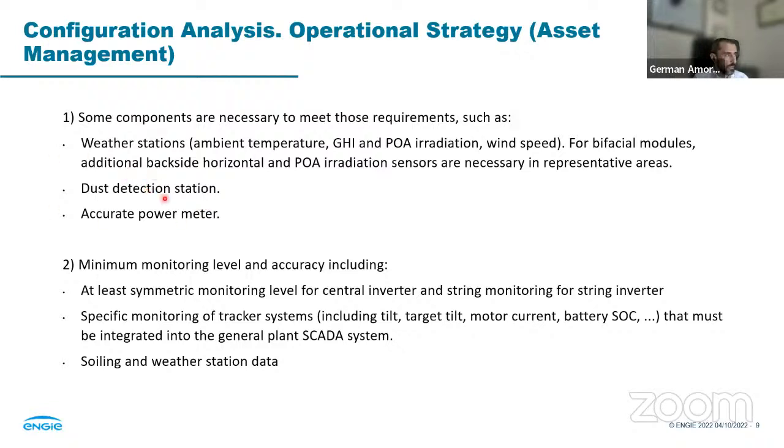We have a soiling station, a dedicated device to detect the percentage of soiling, and for sure a weather station and other meters, and a proper monitoring level. Always it is possible to have a dedicated tracker system monitoring, and for sure a proper normal solution for monitoring of inverters.